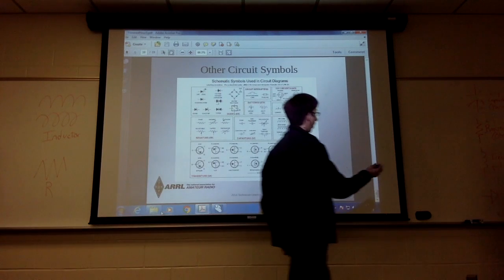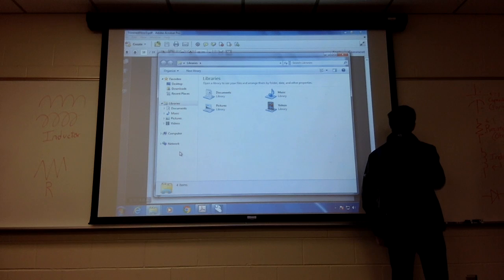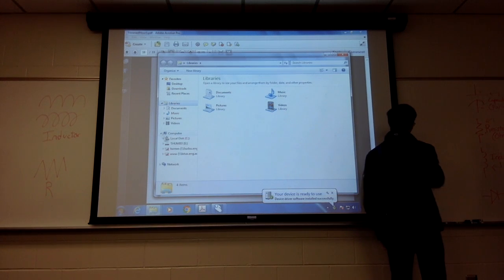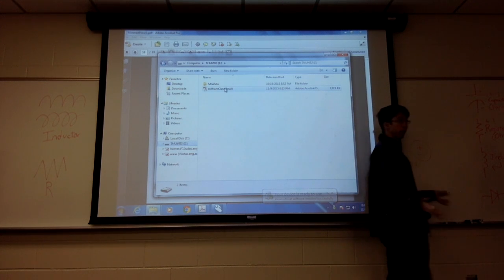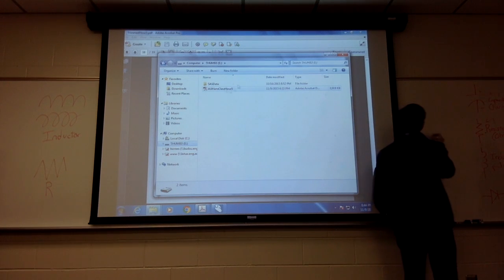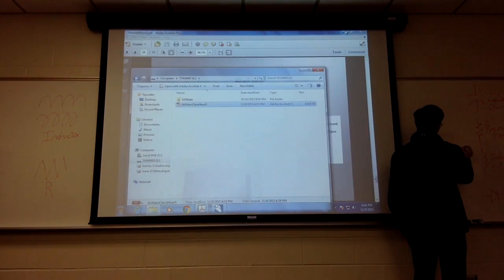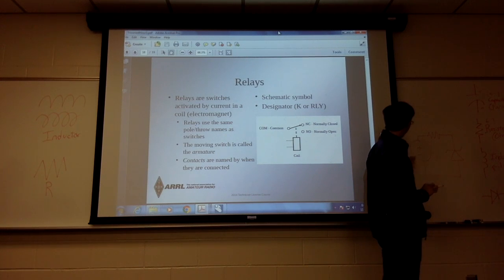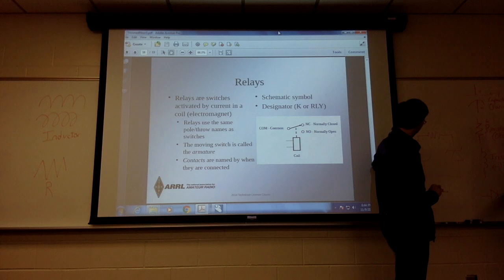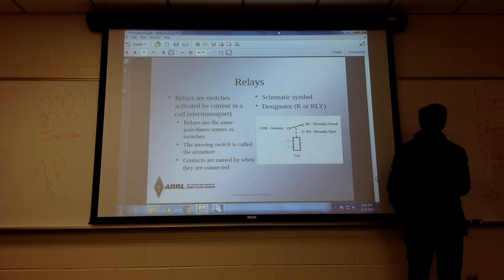For instance, a very common circuit would be: we have some voltage source here, and maybe it's 12 volts, maybe it's 13 volts, maybe it's 6 volts or something. We'll add a resistor here to limit our current, and then we'll have a Zener diode here. Now we have some predetermined Zener diode. Let's say the 5.2 volt one I was talking about earlier sounds pretty good. So this is a 5.2 volt Zener.